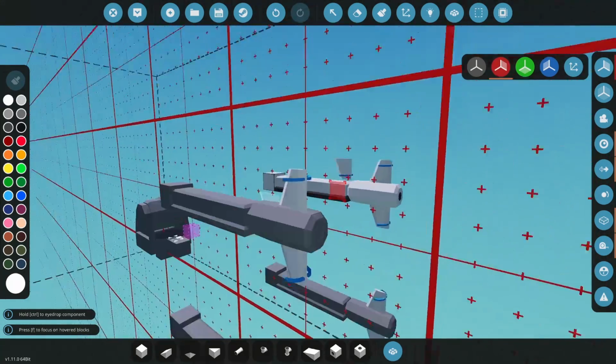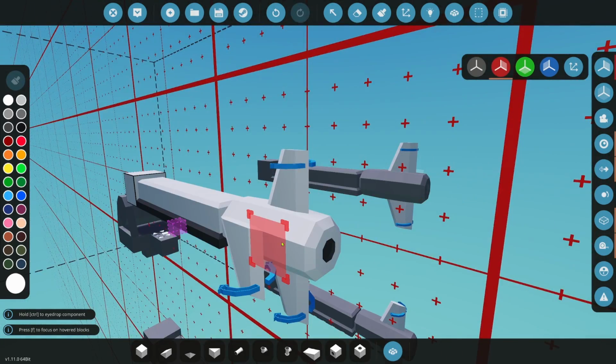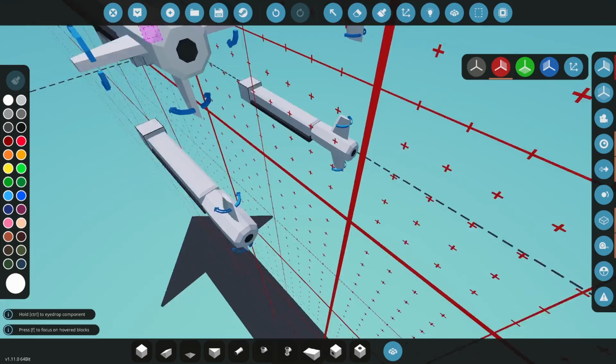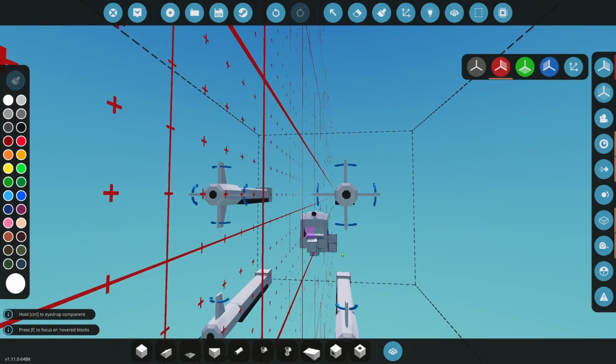All right, next thing, the top 2, we want them to go up. If we look at this, we want the solid arrow going down. That's going to increase the angle of attack of the fin, causing lift, so these will go up. So solid down on the top, and we're going to do both sides. As you can see, all solid downs on the top.